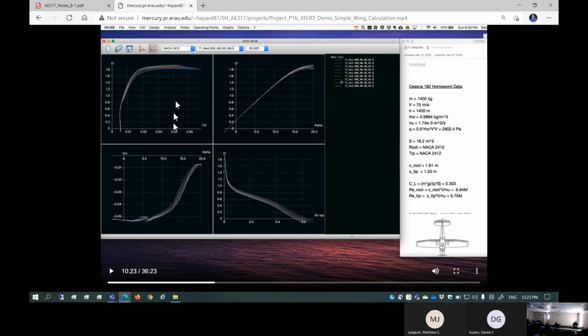This only shows half of it because this is NACA 2412, which has a camber. So in order to take a look at the full picture, you need to go to the other side too. But anyway, this is a CM and alpha plot. You see this hump here. This is the transition from laminar to turbulent. So you are going to see the transition point right here. This is the CM versus alpha plot over the range of alpha from 0 to 20 degrees.